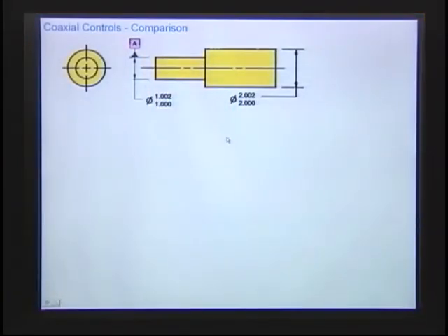Now here's another case, little things that I see people sometimes having a little trouble with. That's why I thought I'd do this bit of review. You're going to have some examples in the workbook where you're going to have a shaft. This here is a part, this yellow one. You see I have one diameter on this side, and then a diameter on the other side. This one has size, and this one has size, of course. This one here is called off as a datum. The small one is a datum. Now, if I want to keep this one on the center, what symbol should I use?